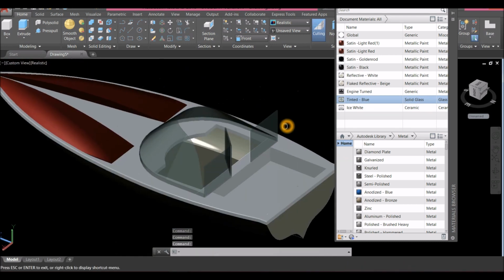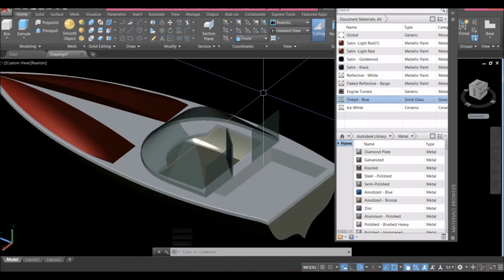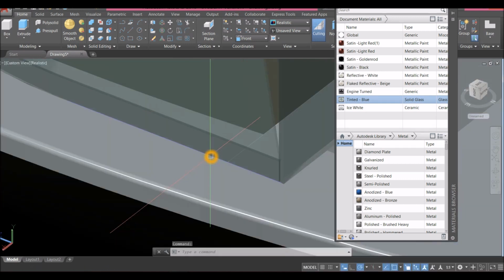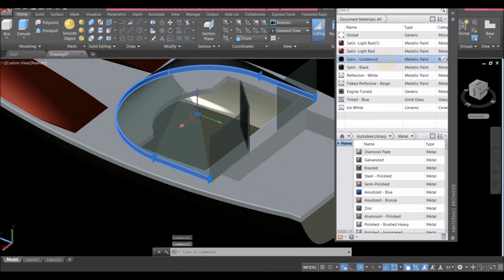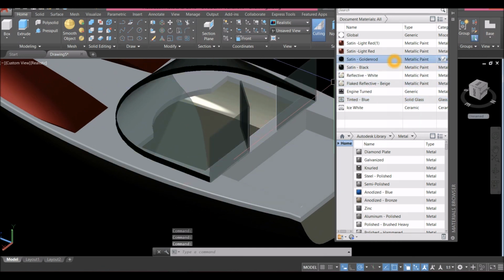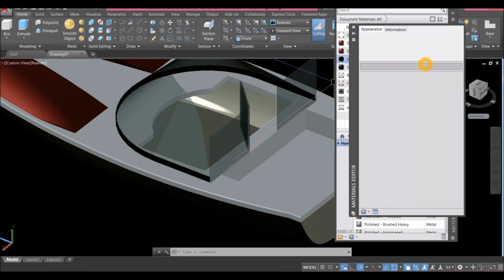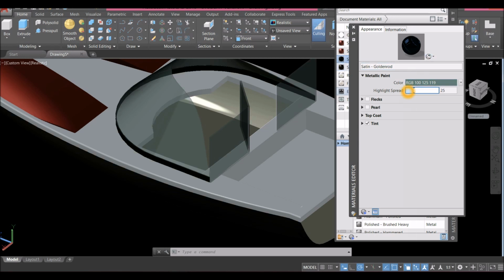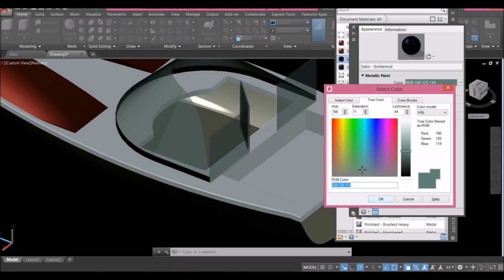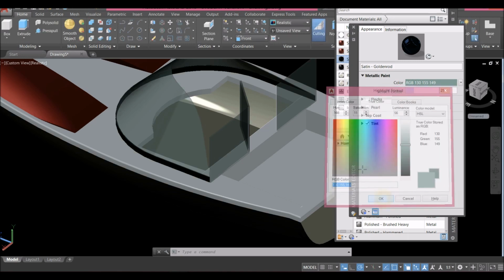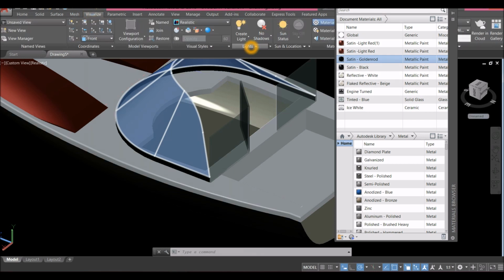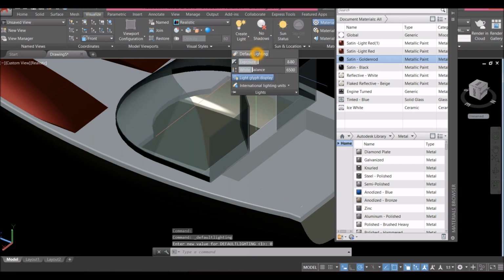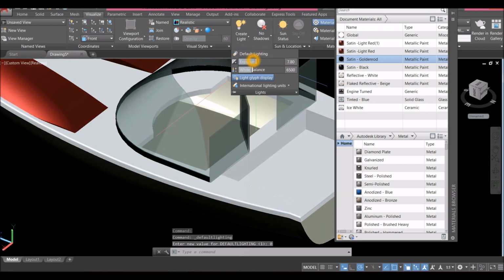Now I'm gonna apply foil gold, or this golden rod, for these objects here. So select this one and select golden rod. I'm gonna adjust the color, so click that. And change maybe lighter. Go to visualize, select these lights and adjust exposure setting.